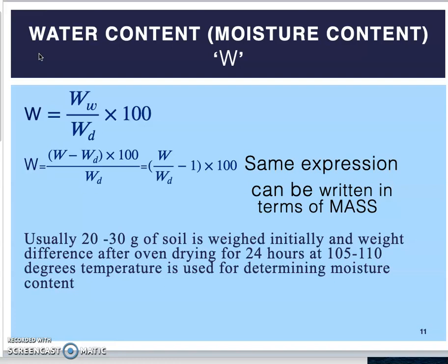The moment water enters the voids, its weight increases. If you have noticed, a lot of landslides occur in monsoon. Why is that happening? The soil mass was otherwise very stable on that slope, but the moment water has gone inside, it has become heavy, and now it has no other options. Obviously, there are other reasons also which trigger landslides, but yes, the moment water enters the soil mass, it becomes more vulnerable to this kind of damage.